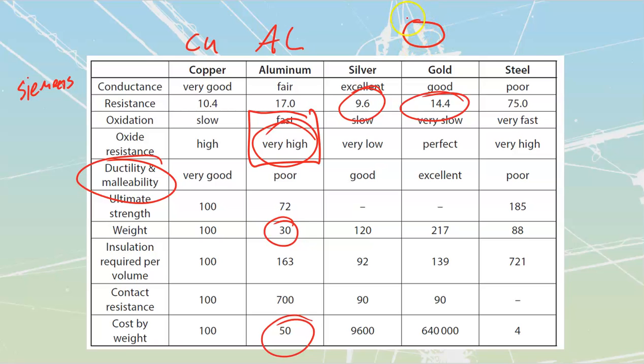This is why when you're dealing with aluminum, you need to have a lug that is sized correctly. Just because we can fit a wire underneath there does not mean that we necessarily should. What I'm talking about is if I've got a lug that is rated for 2/0 over here, and I decide that I'm going to place, we'll say, a number 8 aluminum underneath there. This hole over here is rated based upon that size. And if you've worked with these lugs before, they're going to have a threaded insert that is going to drive down, and usually that threaded insert is going to be flat.